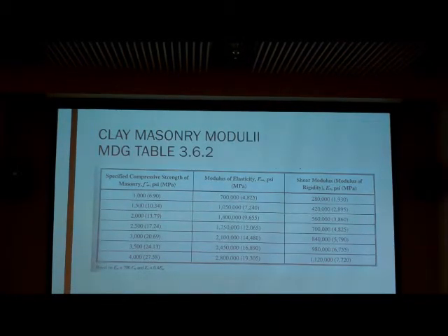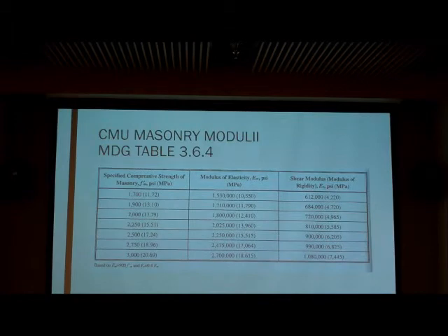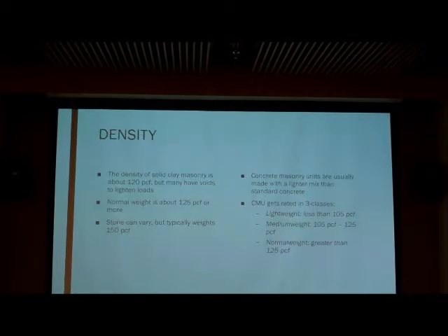Yeah, so here's some modulus of elasticity and the rigidity modulus for clay masonry, and there's also one for CMU masonry. And both these properties just vary on the strength. So when you're talking to the manufacturer about what you're going to use, you'll find out all this information and can calculate that. The last thing I'm going to talk about is a little bit about the density of the